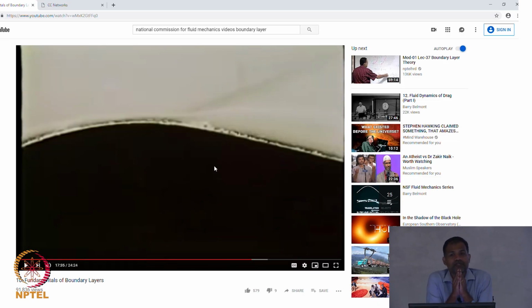Now, something that I did not tell you yet: we really did not distinguish the laminar boundary layer from the turbulent boundary layer. We also talked about separation in the boundary layer. A turbulent boundary layer means a larger Reynolds number, and a larger Reynolds number is a representation of larger inertia. So in a turbulent boundary layer, separation occurs at a later point, not as easily as in a laminar boundary layer, where the fluid might get separated.